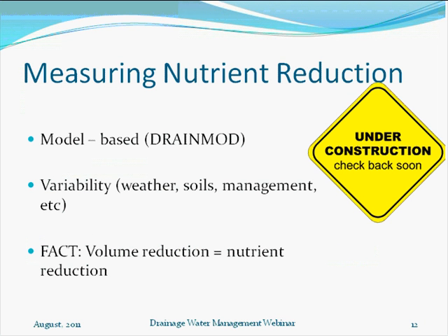How are we going to measure the effects that we have out there on the field? I like to give an example when I talk about this of RUSLE2. NRCS people are excellent at doing RUSLE2. This is a model that we run all the time to take credit for sheet and rill erosion and the reduction that we do out there on the land. Are we out there with a beaker measuring how much less soil loss there is? No, of course we're not. We're doing it in the computer on a model.